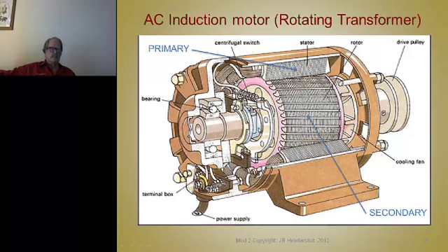This has a centrifugal switch because it's operated with single-phase power, but it's really wound for 2 phases, so it'll start as a 2-phase motor. Then when it gets to a certain speed, the starting winding is opened through a centrifugal switch. The circuit's open, so no current flows into the start winding, and it just runs very inefficiently with only 1 winding.